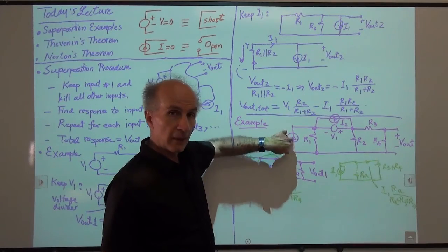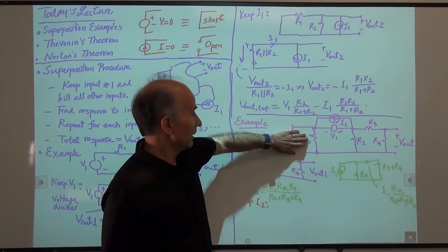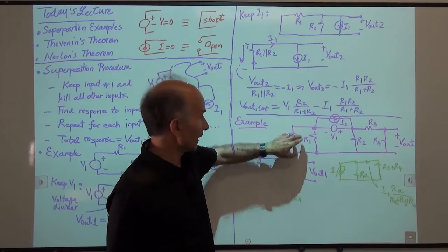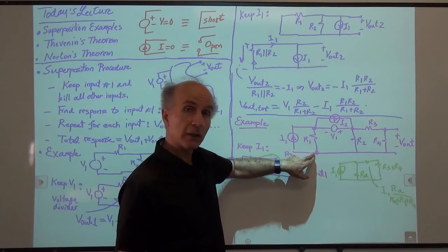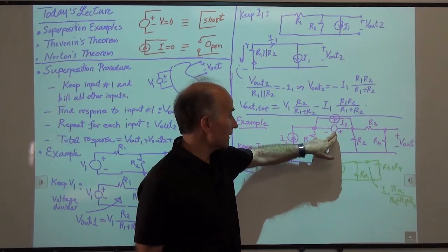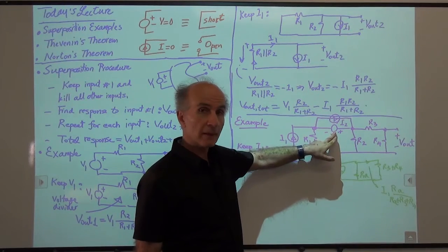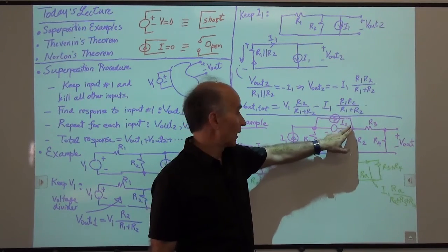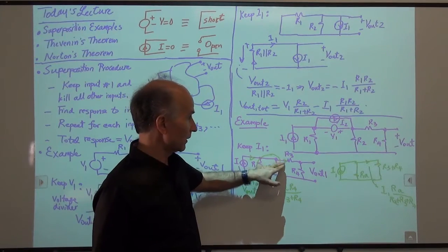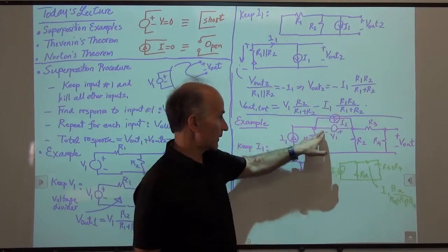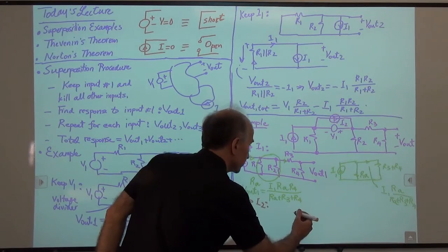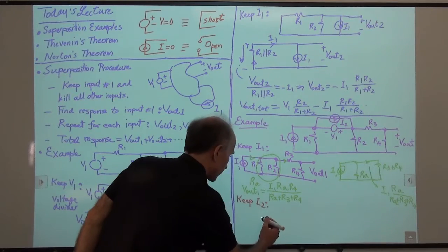What does it mean? It's an open circuit. Open circuit means cut this out, keep these floating, don't connect them to each other, right? So that branch is completely gone because no current can flow through it. And then we have to set this to 0. When I set this to 0, what happens? Well, there's a short piece of wire here, just with the way we had it before, between R2 and R1, remember? We had a piece of wire, so it's the same thing. Okay, so the circuit reduces to, let's see if I can draw it here.